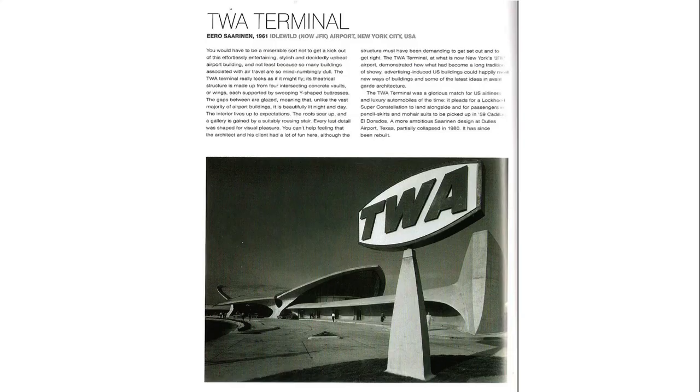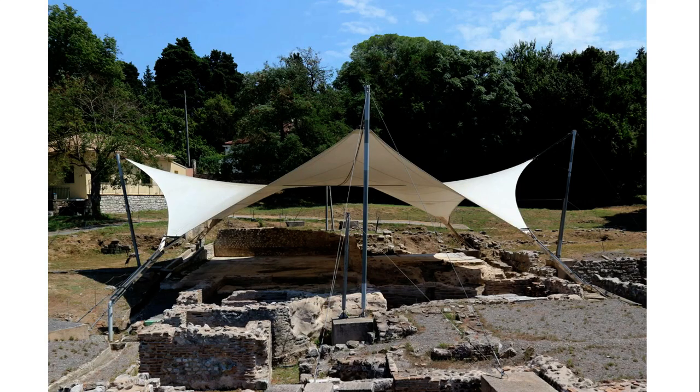Here's some more beautiful structures of the same ilk. And as I said, exactly the same principle operates using fabric structures. These anticlastic shapes develop naturally by pulling on fabric. Of course, there's some pattern cutting going on, isn't there? And there's some important detailing. These edges are all reinforced when you're designing fabric structures.